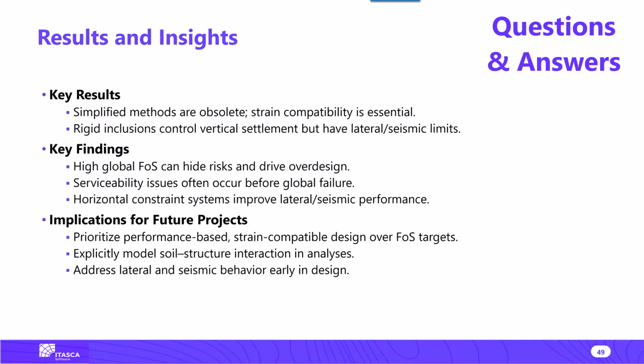That takes a little bit more time though, because I have to do it gradually. I have to implement this process in such a way that I don't create perturbation. Or a simple one would just be to impose a K-note. You modify the K-note after the model is in equilibrium, essentially increasing the horizontal stress.